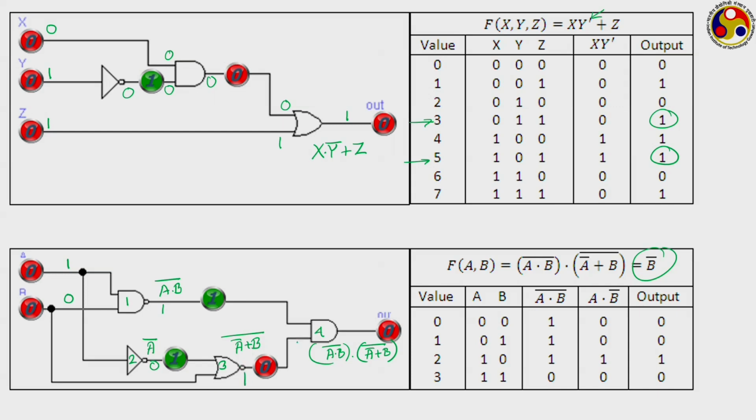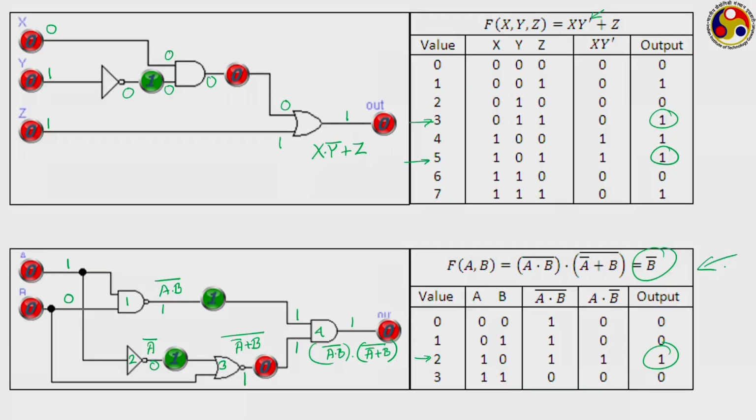So, this AND is receiving 1 from the lower side, this gate number 3, and another 1 from the NAND operation. So, this is a standard AND gate. So, we are getting 1 as the final output. So, for 1 0 operation, this is the final output. This is the only case we are getting 1 in this particular scenario. For all others it leads to 0. This way logic gates can be combined and we can get any kind of outputs. Look at this particular example specifically.